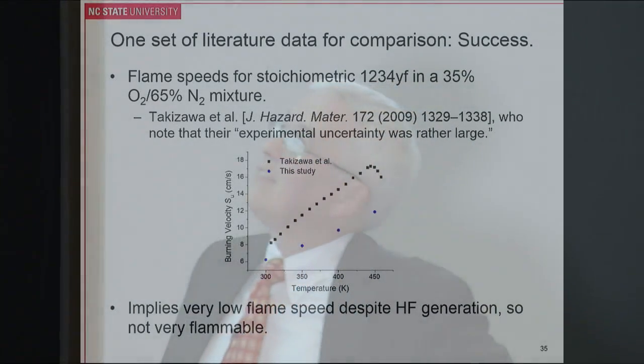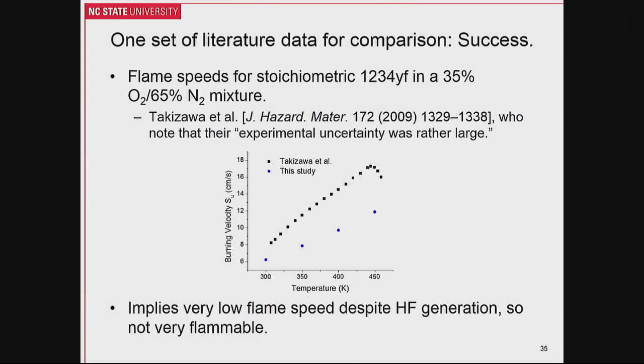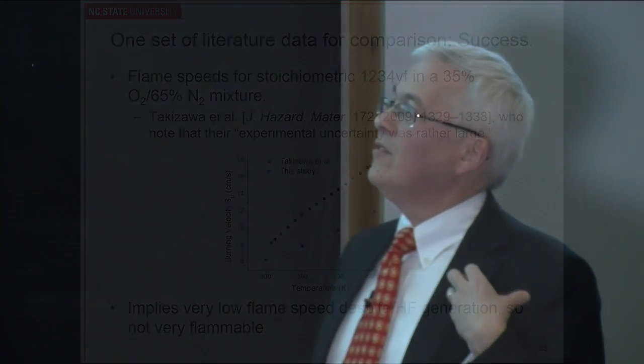As it turns out, there's only one set for YF of any flame data that we could find in the literature by Takizawa, who did caution that experimental uncertainty was rather large. Nevertheless, the agreement of this study is sufficiently good. It's way down in this order of 10 centimeters per second range that says it's pretty non-flammable, not too much to worry about. So again, we were able to see this low flame speed suggesting it's important, but it also showed that HF, hydrogen fluoride, was being produced. So it illustrated the sort of pollutant issues that come up.